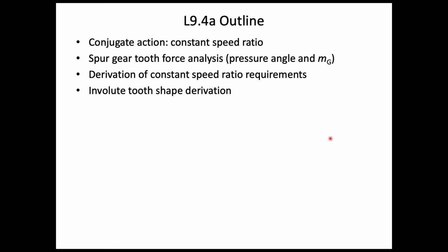The term that we use to describe this geometry is involute. So we're going to look at methods for generating involute tooth shapes. Next, we're going through a physical illustration of involute shape generation, and I hope that this provides a lot more intuitive insight into how this particular gear shape works in providing conjugate action.